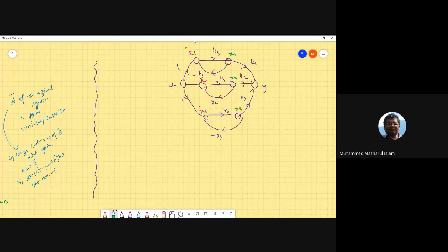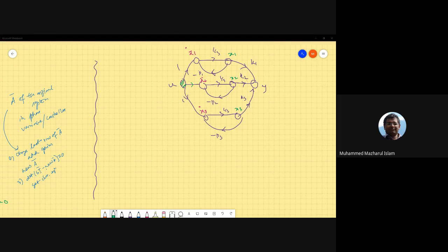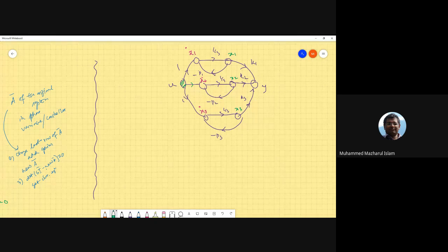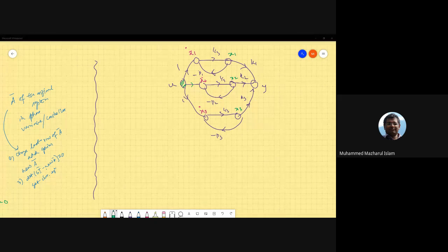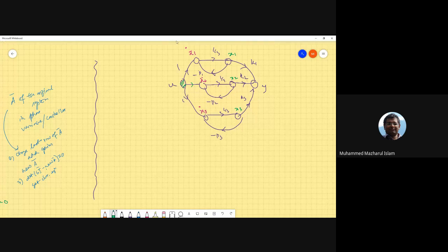Now what's important is to understand that the input U feeds into each of the states. See, U is inside X1 dot, X2 dot, X3 dot. So any change in U will affect X1 dot, X2 dot, as well as X3 dot. So systems where the input has a direct connection with the states somehow, either in this kind of parallel configuration or in the state space, in the phase variable model.